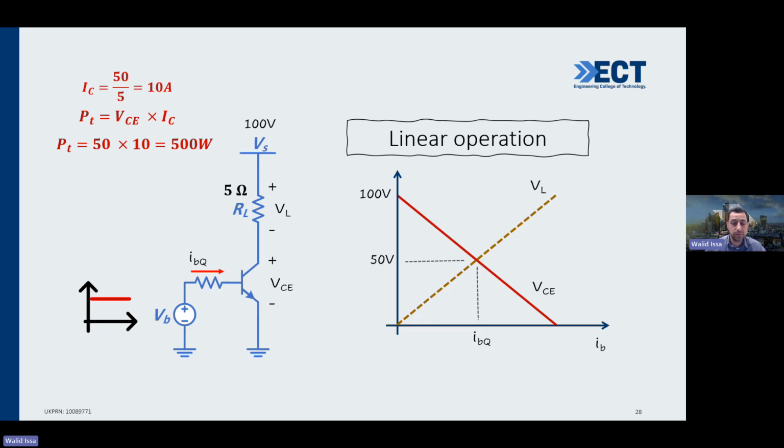This approach has been used before, for example, in musical instrument amplifiers, for piano, for other things, for audio amplifiers. They were really losing a lot of power. 500 watt. There is no transistor that can lose 500 watts. So they were paralleling transistors together on a big heatsink with a fan as well, using different transistors at the same time in parallel to dissipate that 500 watt.